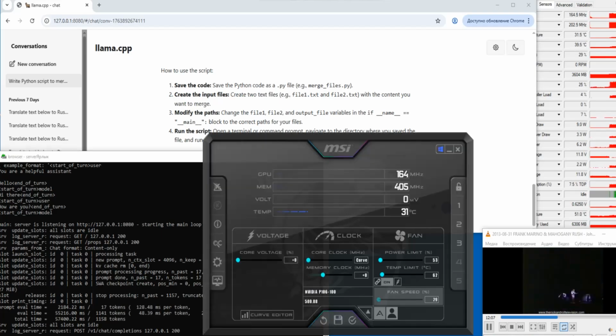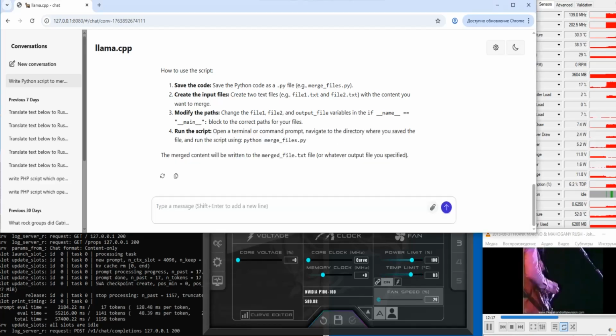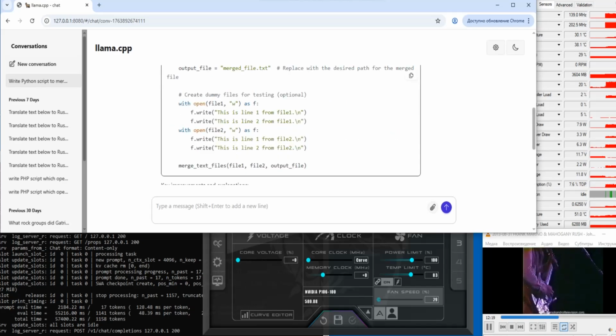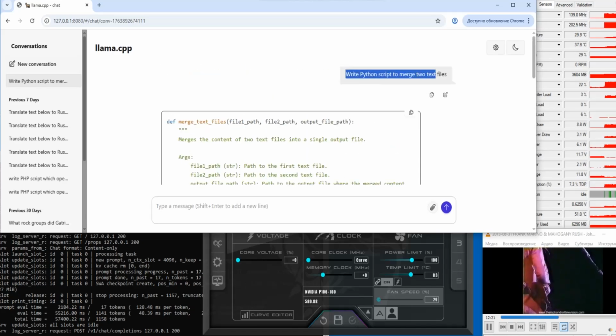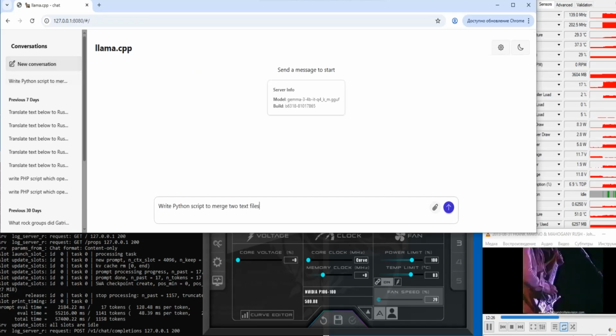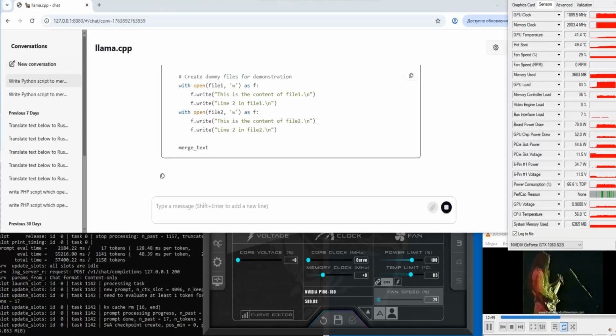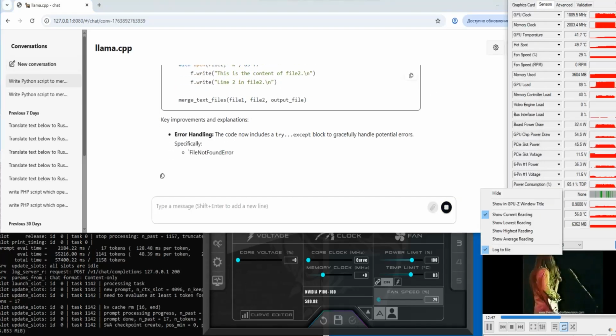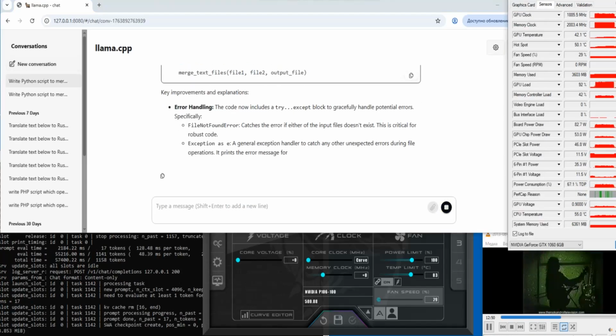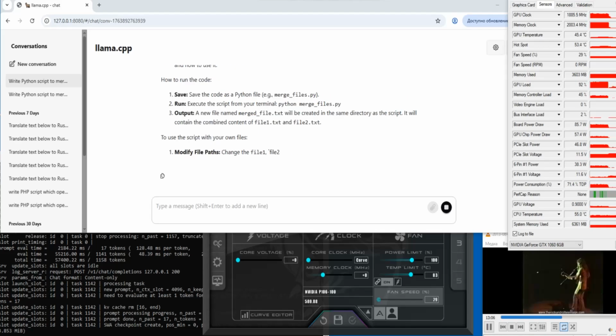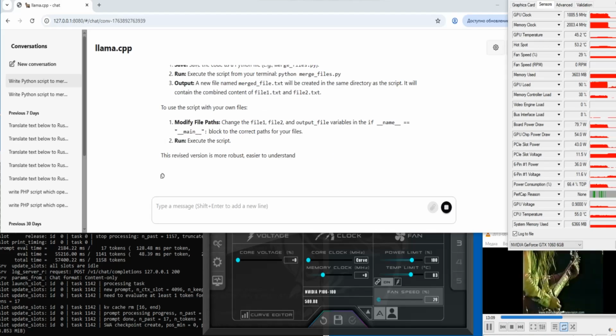Increase the power limit to 100% and try the same request again. By the way, you will certainly ask, why test the power reduction? When I first put the video accelerator into the computer, there was one power supply of 350 watts, and periodically, especially during the launch of picture generation through ComfyUI, the power supply was not enough and the computer turned off suddenly. I got a second, not very powerful supply just for powering the video accelerator.